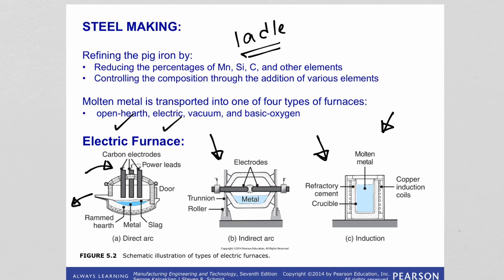And the vacuum furnace. The vacuum furnace is similar to the induction furnaces, but as the name implies, the air has been removed. The cooling is also achieved using an inert gas, and this way we can remove the gas impurities from the molten metal and prevent oxidation. Therefore, vacuum furnaces produce high quality steels.